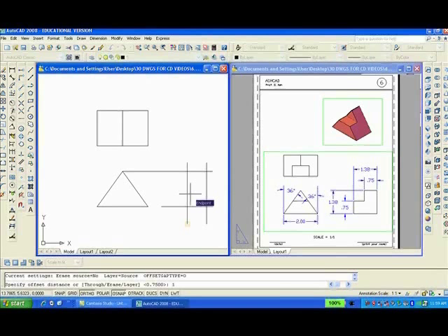Offset 1.38, enter, from here over to here. Now I'm going to offset, so I just repeat, hit enter twice. 0.75, enter, and this line goes up. I can type F enter for fillet and clean up. Try it again. F enter, hit escape whenever you're in trouble. I can fillet these two, hit the space bar, fillet these two, hit the space bar, etc.